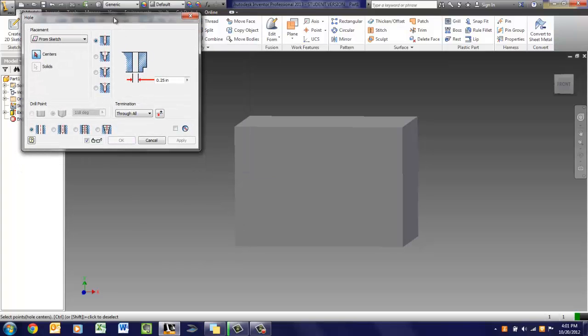So first, what you need to do is identify where you're going to place your hole. I have chosen a view, but I can also place it from a sketch. If there's an actual sketch that I've placed there from the 2D, I could use that. I can do linear, which is easy so long as you have two edges to work from. Concentric would be aligning the hole with the center point of another circle or arc. Or if there's a particular point that you'd like to use to create the circle. For today, though, we're going to use linear.